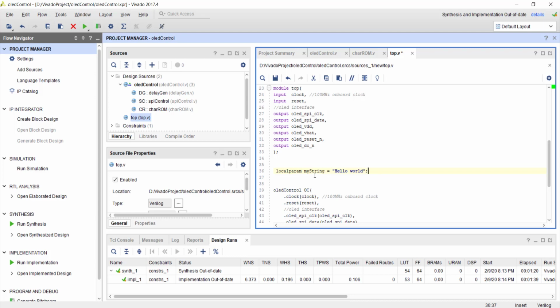Now if you write like this in Verilog, what is going to happen is, he will make a small memory inside the FPGA, and that memory will be filled with the ASCII code corresponding to each of these characters. Again, this is not like our software. This information is not stored in RAM or something. So using LUTs and flip-flops, he will create a memory, and inside that memory he will automatically store the ASCII code corresponding to each of these characters, because you wrote it like a string.